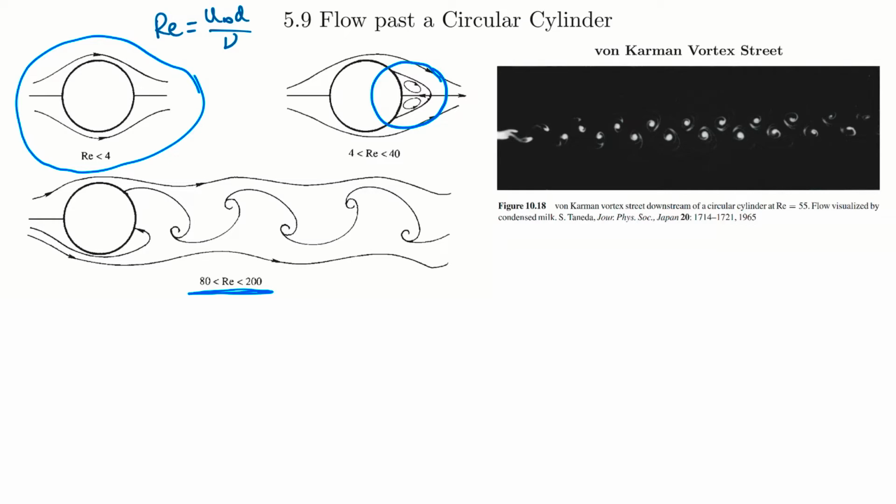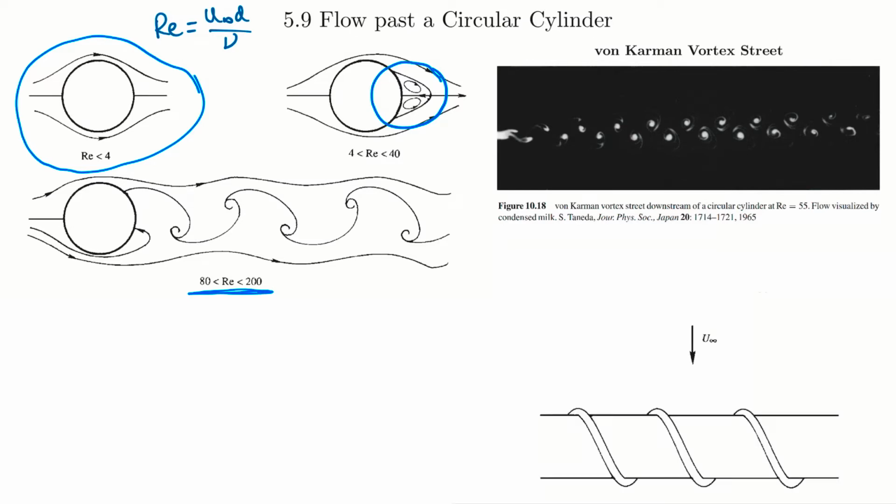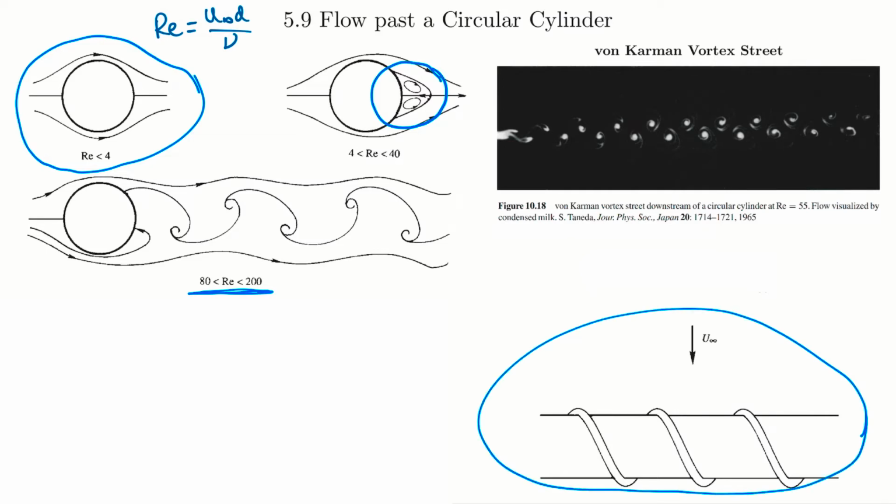So the engineering of structures like suspension bridges or oil drilling platforms are designed so that they break up the coherent shedding of vortices from cylindrical structures. You can do this, for example, by including spiral blades that protrude out from the cylinder surface, and they'll break up the span-wise coherence of the vortex shedding, forcing the vortices to detach at different times along the length of these structures. And that's shown in examples right here, of these spiral blades.